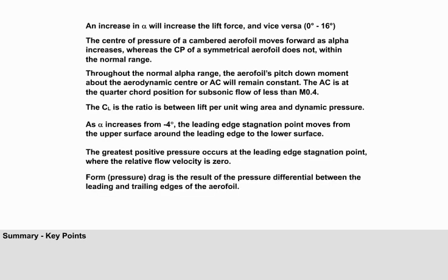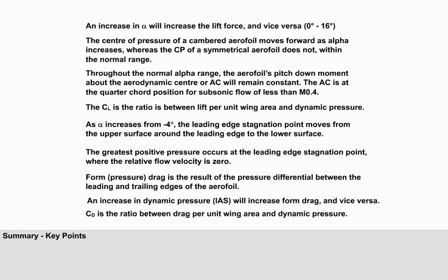Form, or pressure, drag is the result of the pressure differential between the leading and trailing edges of the aerofoil. An increase in dynamic pressure, that is, indicated airspeed, will increase form drag, and vice versa. The coefficient of drag is the ratio between drag per unit wing area and dynamic pressure.